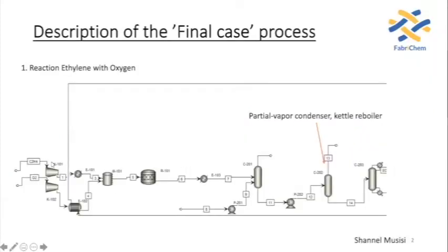At the beginning of the process, ethylene and oxygen gas are compressed at 20 bar. Ethylene passes through a normal heater operating at 270 degrees Celsius, whereas oxygen passes through a heat exchanger with an exchanger duty of 169,244 calories per second. Some of the heat will be transferred to the second last distillation column towards the end of the process, and the excess heat from this distillation column will be recycled back to the heater via a splitter to further heat the oxygen.